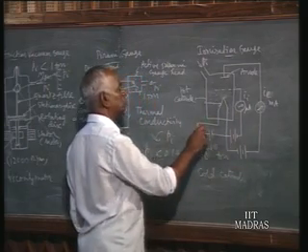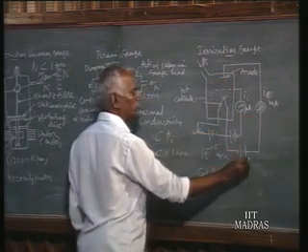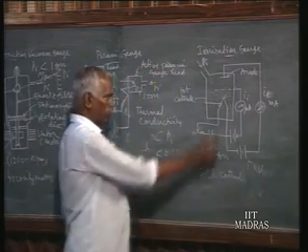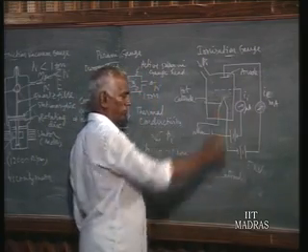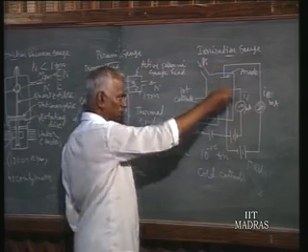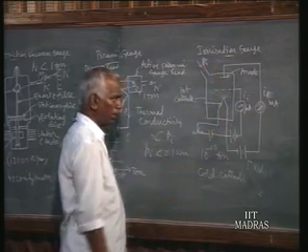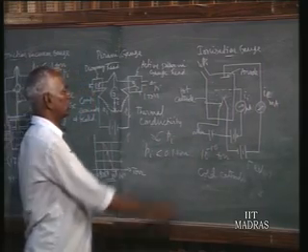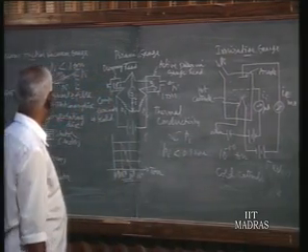Then to pull the electrons, you need a high voltage, of the order of 5 kilovolts. If you have a cold cathode, then this battery will be in terms of kilovolts, and you can pull these electrons. As they race, they hit the molecules, proportionately we have current, and accordingly we calibrate in terms of the vacuum. So that completes the methods of measurement of vacuum.